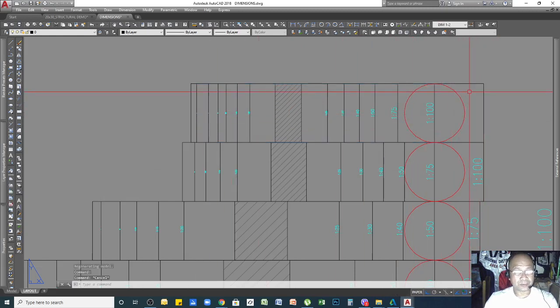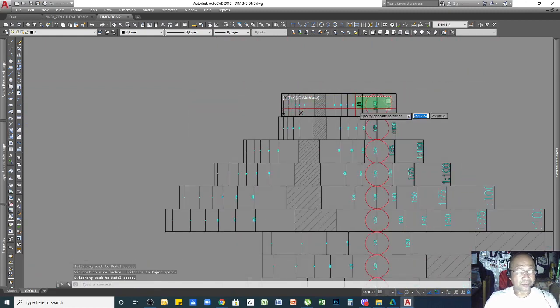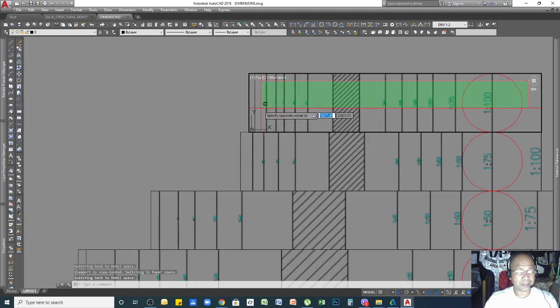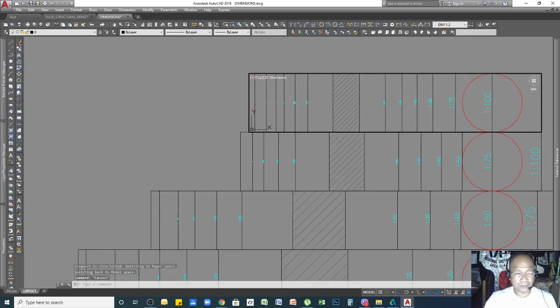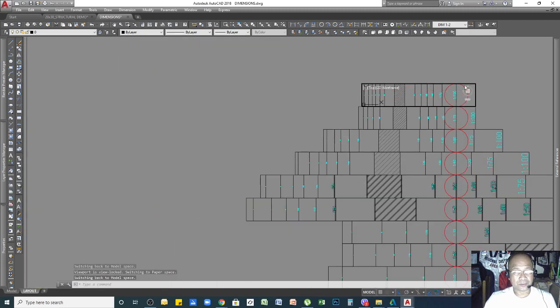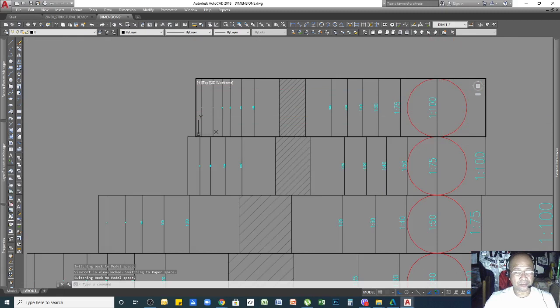When I double click here, I go inside the box. You see I can highlight or modify the content of my drawing, which is basically the same content as in the model space. But take a look below. This setup is set to 1 is to 100 and I already locked it, meaning I cannot change that anymore. It's locked. That's how the dimension at 1 is to 100 appears, using the 1 is to 100 scale.